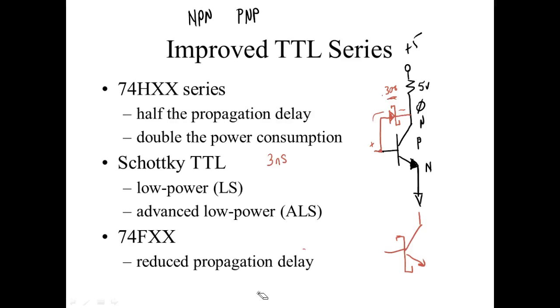Bipolar transistors, it takes a current to control a current. And then, of course, when we take them into full saturation, we have problems getting them out, right? You understand that? Plus, they consume quite a bit of power. So what they were doing is they were looking for an extremely low current capability, low power circuitry, for when we weren't concerned with speed. So the next transistors that came out were ones that we refer to as metal oxide semiconductors.